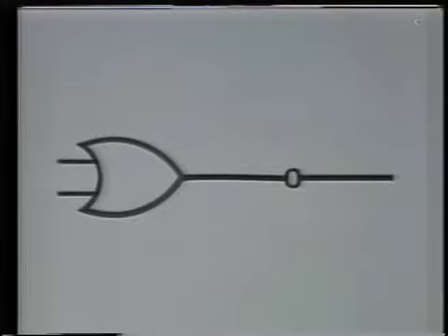In this case, let's take 2 0 levels. If we have 2 0 levels at the input to an OR gate, we will have a 0 at the output of the OR gate. If we have a 0 there and we pass that through the invert symbol, that will give us a 1 at the output. This method of analysis will apply to all NOR gates.